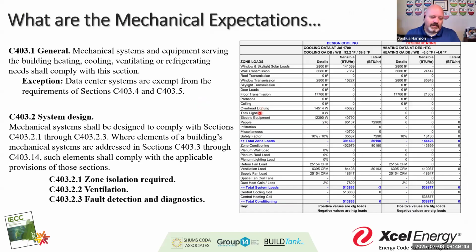Again, I do it all the time, where I read those Manual J's, those Manual N's, those heating load calculations for commercial projects, and we've got the wrong design values, right? We've got the wrong insulation values. I had one the other day where the duct system was identified as coming from an air handler that was not even connected to that section of the building. And, oh, well, we didn't notice that.